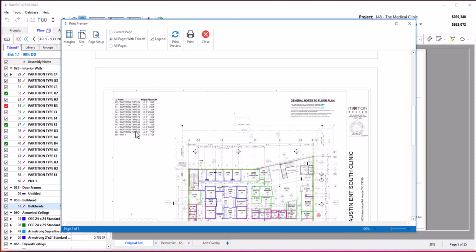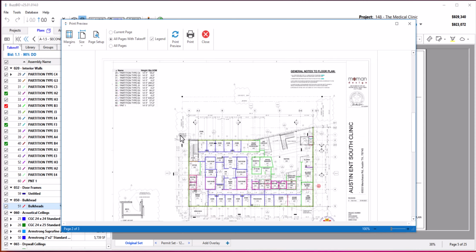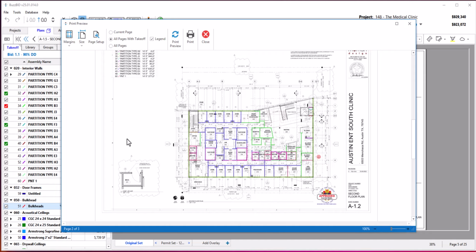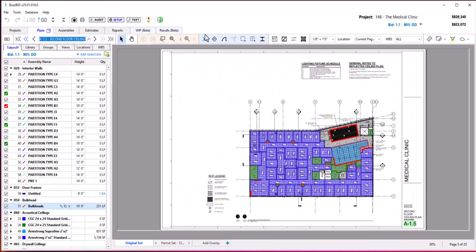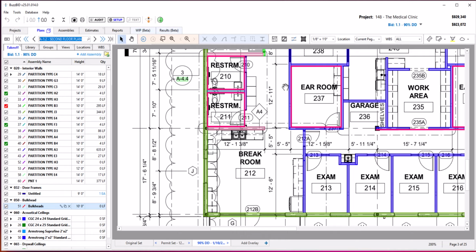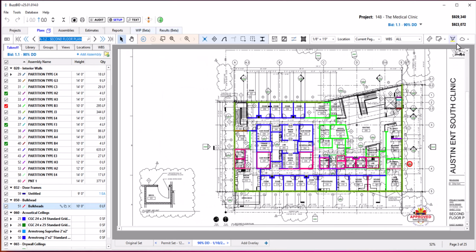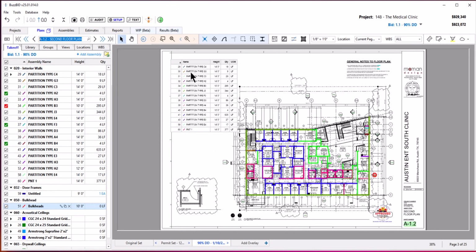If you decide that on this page you want the image legend to be down here in a different location, the way we do that is we go to the page where we want to turn on the image legend, and the image legend is turned on under the annotation tools, upper right hand corner here, if you can see this. And I'll go to the image legend. It puts itself there by default.